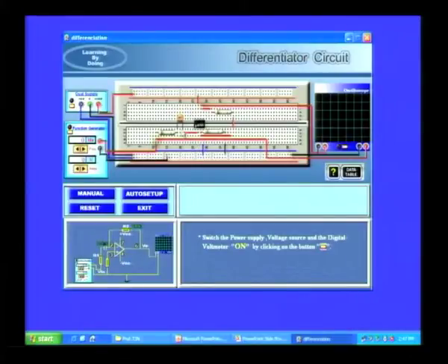So, you have 270 ohms in series with a 0.01 microfarad capacitor, and you have a 10k resistor connected to ground at pin number 3, which is the non-inverting input. You also have a 10k resistor in the feedback between the 2 and 6 terminals of the op amp. So, it is exactly the same as what you have here, and that has been wired.